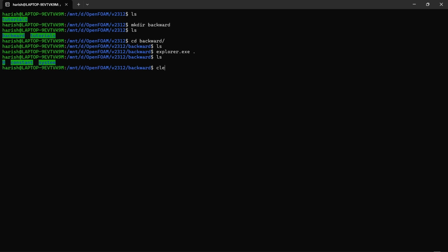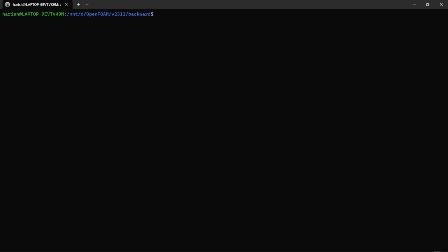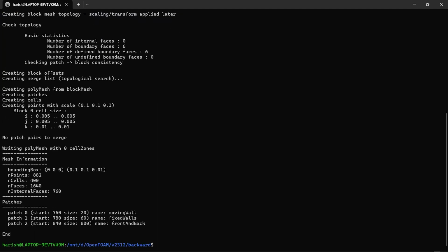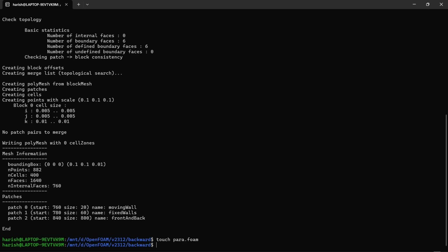and system, right? Okay, now this case is going to act as a template for us so that we can build our case on this. This is an entirely different case, which is a cavity case, but we are just going to use the template so that we can build our case here. Okay, this case already has a blockMeshDict file. So I'm going to run blockMesh. It is successfully generated. Now to view that, you will type touch space para.foam or case.foam, it doesn't matter, something